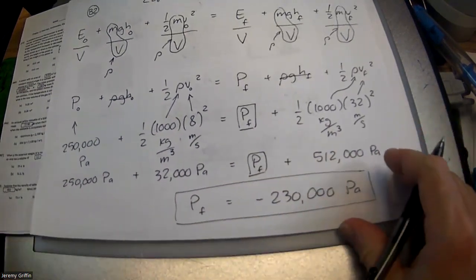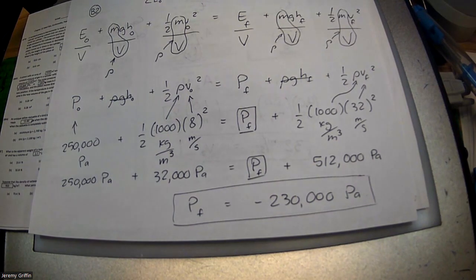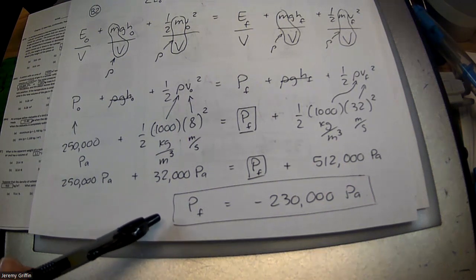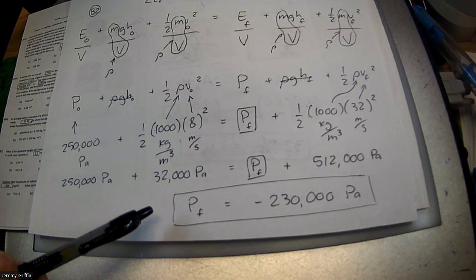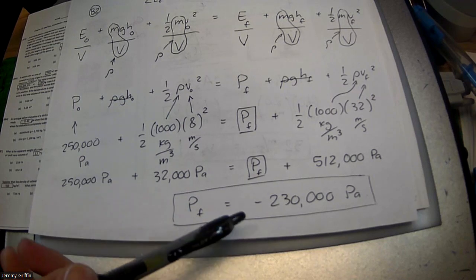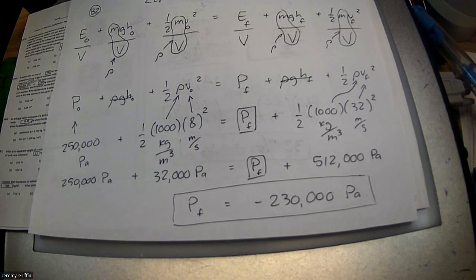How about this? We're sitting in a room right now. What if I vacuumed all the air out of this room? How many pascals of pressure would be on the walls? How about 0, right? So can pressure really go negative? Yes, for liquids. This is one of the differences between liquids and gases. Gases can go down to 0 pascals, and then you're just at a perfect vacuum. Liquids can go negative. You can have a negative pressure. And that means that the water's actually like vacuuming on the pipe walls, like pulling on it.